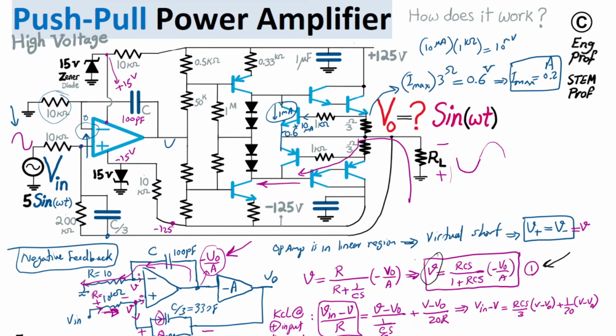So that is the maximum current that the circuit would allow. And then after that, what happens is when the current is trying to increase more than 0.2 amp at the peak of, let's say, a positive cycle, this transistor turns on, immediately grabs the current that is coming from the current source toward the Darlington transistor, and redirects it toward its collector. It doesn't let the extra current go through the base of the transistor.